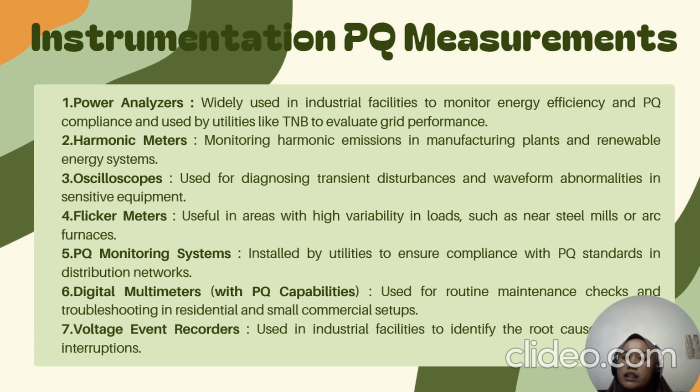Sixth, digital multimeters with PQ capabilities, used for routine maintenance checks and troubleshooting in residential and small commercial setups. Seventh, voltage event recorders, used in industrial facilities to identify the root cause of power interruptions.